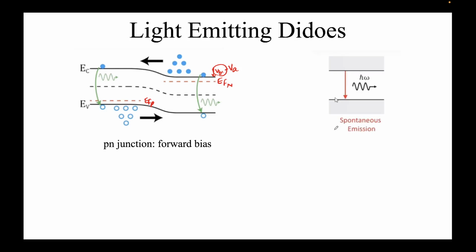Okay, so this light emitting diode is nothing but, very simply, a forward bias PN junction, right? The only thing that is happening is that we are injecting some current from the battery, correct? So what we have is a huge supply of electrons in the conduction band, right? And they are going to drop over here to recombine with the hole. So this is essentially based on recombination of electrons and holes.